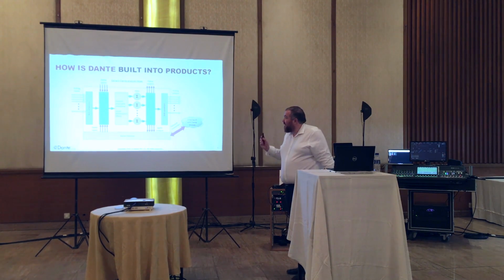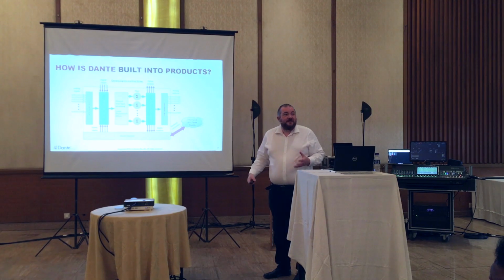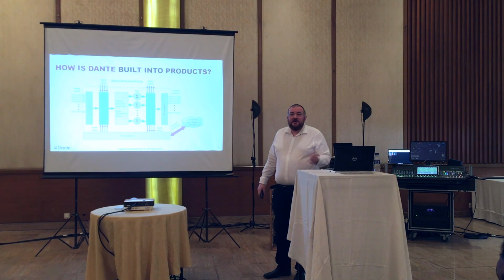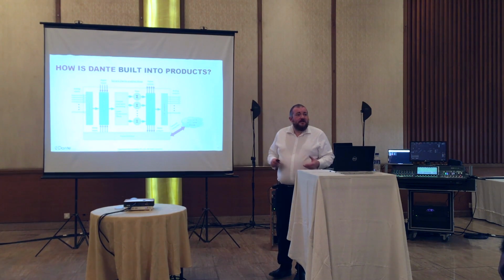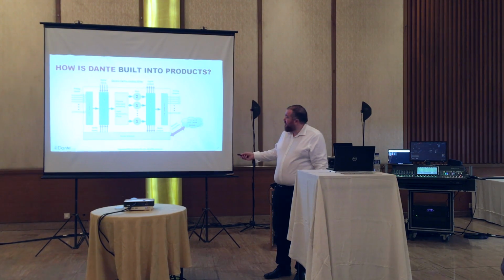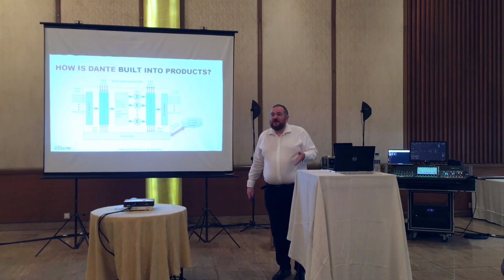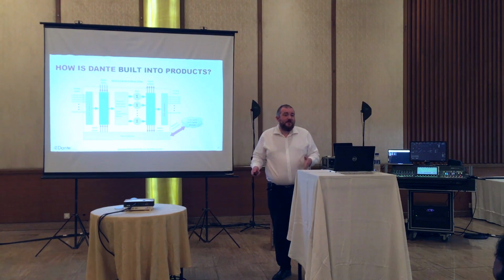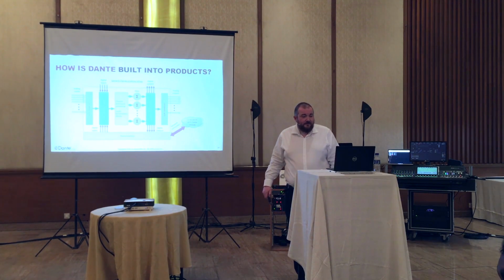We've included this slide because sometimes we've had people say, oh, I've got this device plugged in and channel 1 is not coming up as channel 1. That's because oftentimes people put the Dante module into a system like this, where there's, say, in a mixing console, we have an input routing stage, which then will route the Dante inputs as well as analog inputs. We have the processing section, and then our output routing stage will decide which channel goes where. So just remember, on a lot of devices, you need to set the internal routing of the device as well as the external routing.